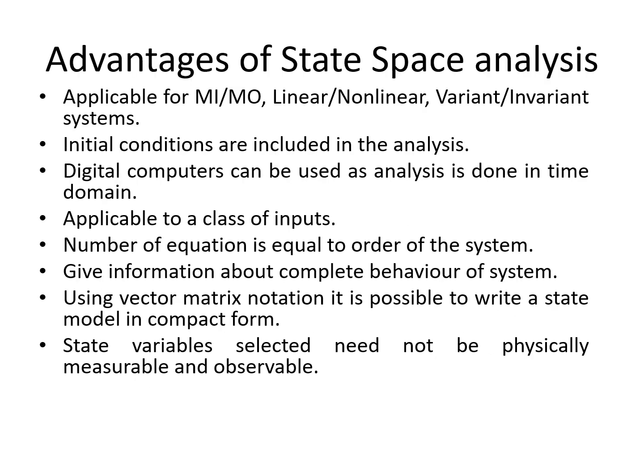Coming to the major advantages of state space analysis: it is applicable to multiple input, multiple output systems, and to linear and non-linear systems, along with time invariant and time variant systems also. Initial conditions are included in the analysis in state space. Digital computers can be used, as the analysis is done in the time domain, and it is also applicable to a class of inputs. The number of equations is equal to the order of the system, and it gives information about the complete behavior of the system.